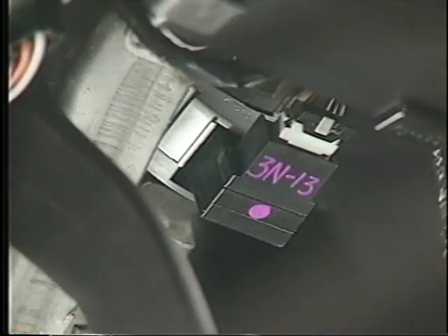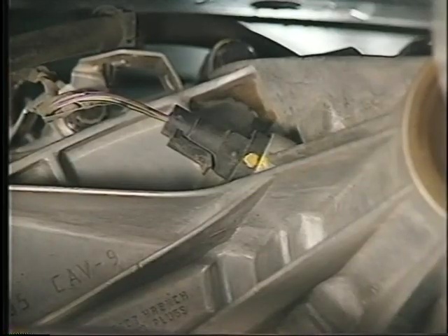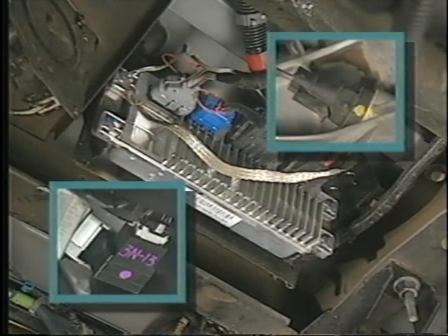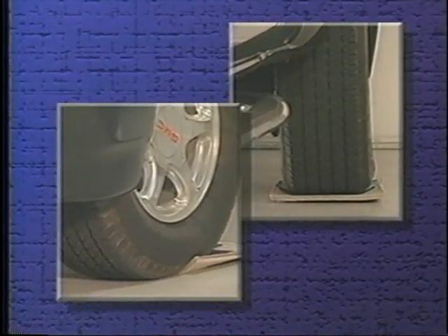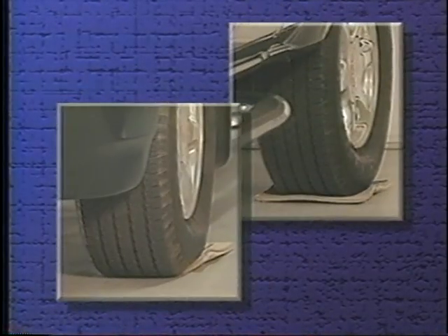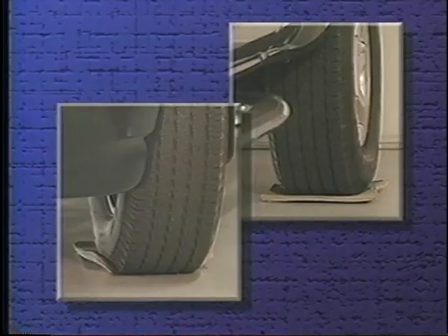the steering wheel position sensor and the vehicle speed sensor. Based on the information from those sensors, the control module will react either in the negative phase, turning the rear wheels in the opposite direction of the front wheels, or in the positive phase, turning the rear wheels in the same direction as the front.